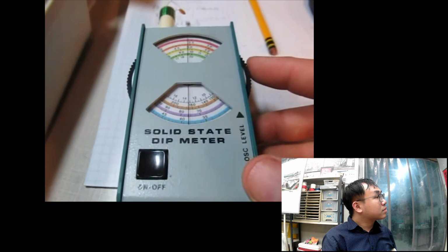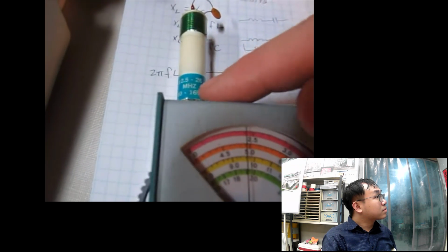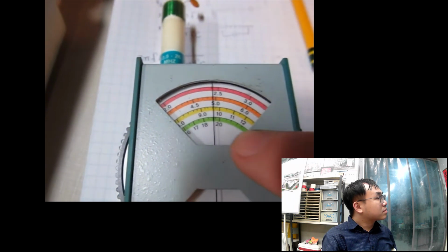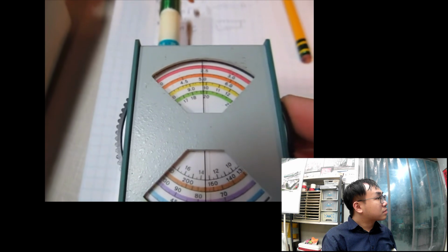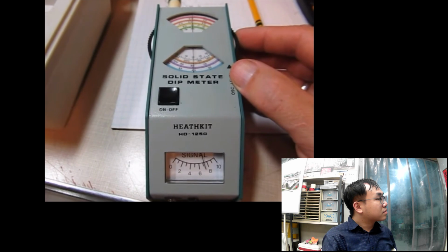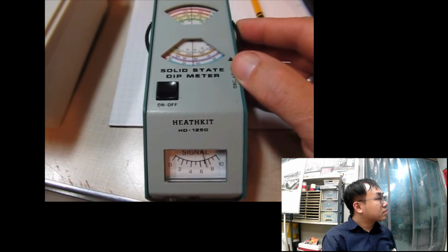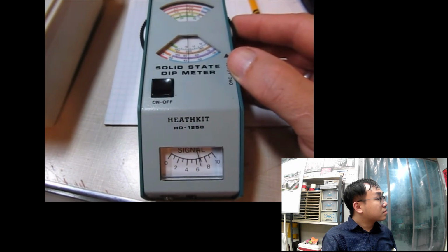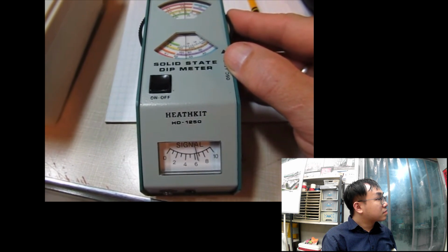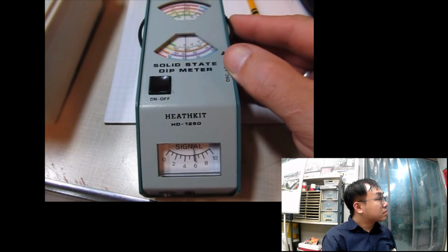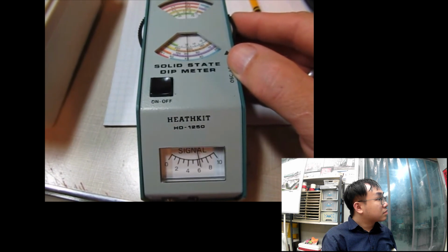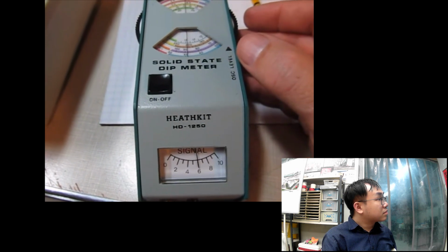Now we adjust the frequency. In this case, the coil we selected is the green coil, so we're looking at the green scale here. As we adjust the frequency of the oscillator, we can take a look at what the meter's doing. Notice I'm rotating this up, watch the meter, and as I pass through the resonant frequency, the meter dips, now it comes back up again. So keep going up, now it's going back up. When I come back down in frequency, it dipped, came back up. And that's really how you use this. You find the frequency of that dip. Now it's right about there.